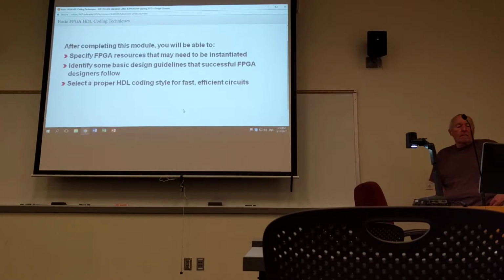But the key thing is that many new customers are disappointed that they're going to have to instantiate some of the most popular FPGA resources into their design. This is now pretty much standard operating procedure in the FPGA industry. What I mean by that is that most customers are prepared to create highly optimized cores with the Xilinx Core Generator or the Xilinx Architecture Wizard utilities, and are then going to have to instantiate them into their HDL. Now, this flow allows users to work around limitations all synthesis tools have with regards to automatically inferring the best FPGA resources.